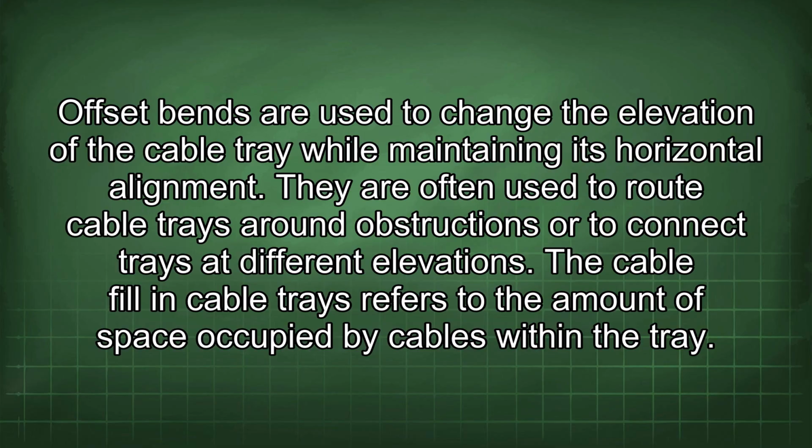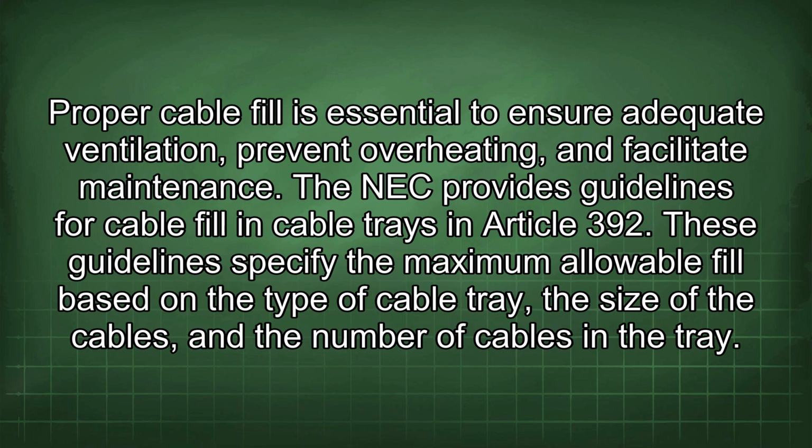The cable fill in cable trays refers to the amount of space occupied by cables within the tray. Proper cable fill is essential to ensure adequate ventilation, prevent overheating, and facilitate maintenance. The NEC provides guidelines for cable fill in cable trays in Article 392. These guidelines specify the maximum allowable fill based on the type of cable tray, the size of the cables, and the number of cables in the tray.